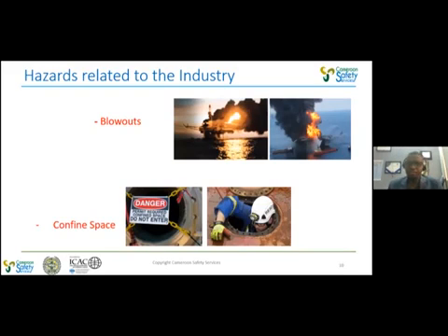Or some activities might require entering confined space, such as going to weld a hole in the confined space, and then later on the gas from the welding accumulates, exposing you to oxygen deficiency, and then suffocating you. So this is also a major hazard, and there have been a lot of reported cases with confined space, and because of that, there have been elaborated procedures that need to be followed by people who want to access confined space for a job they have to do.